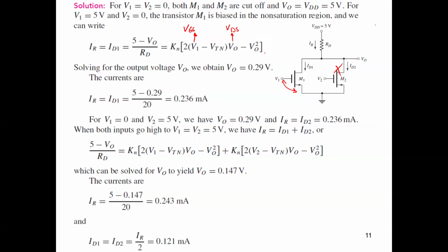Okay. So we just substitute in the MOSFET relation between ID and VDS in the linear mode. Why again, guys, in the linear mode? You don't need to calculate in the saturation mode because you know that this application needs linear operation of the MOSFET. For sure you can start by assuming saturation operation, but by the end it will not work. So from the beginning, you know that this application is for linear mode. We can substitute now in the relations and get our numbers here.